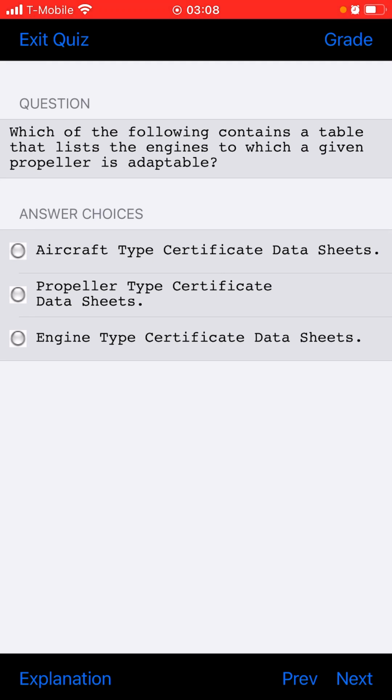An oil analysis program is a trend indicating system. A sample of oil is taken when the engine is new, and the parts per million of each of the number of elements is recorded. Subsequent samples are tested on a regular basis. The trend of the growth of the trace elements is recorded. When the growth of any element is far more rapid than it should be, the engine operator is warned of possible impending trouble. Analysis of the first sample is only a starting point and cannot give an accurate forecast alone.